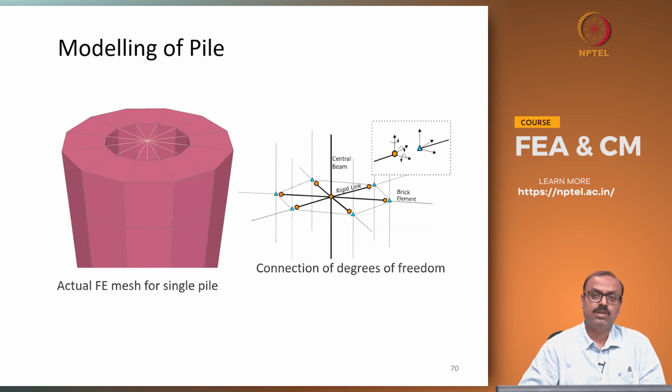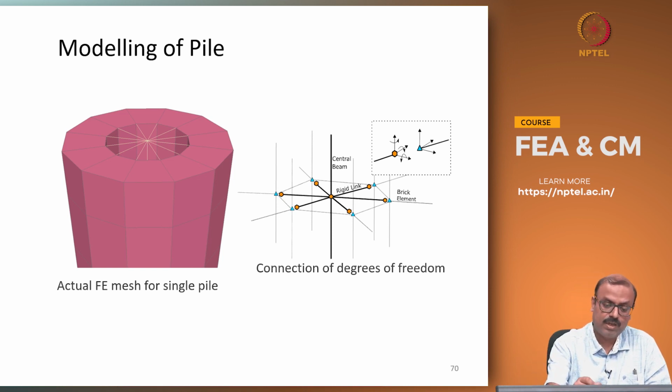Now, the question about the modeling of the pile, as I said earlier: if you are fine with modeling the pile as structure, linear elastic, then there is no problem. However, if you want to include some kind of damage plasticity model to see whether any kind of damage happened in the pile, then you cannot use that indirect method.